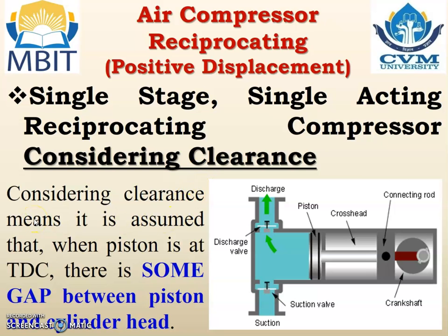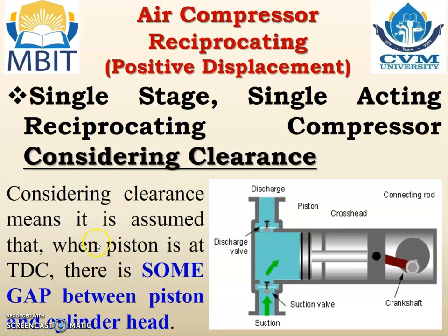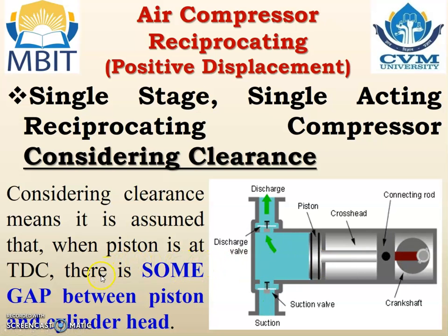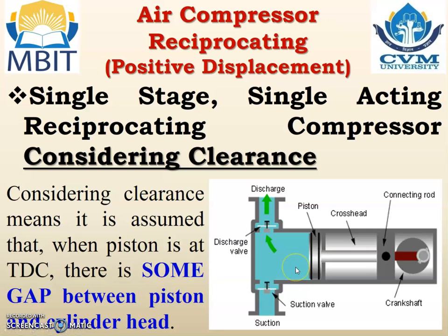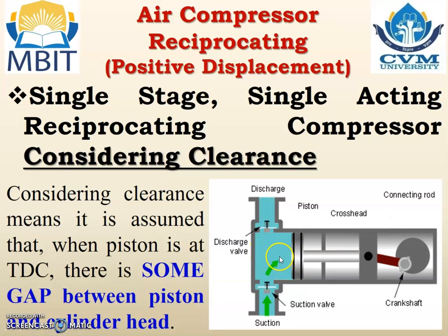Considering clearance means it is assumed that when the piston is at TDC, or you can say at the extreme left condition in the horizontal engine, there is some gap between the piston and the cylinder head. So you can see in the animation, when the piston is at the extreme left, there is some gap. And due to that gap, it is considered that this reciprocating compressor has clearance.